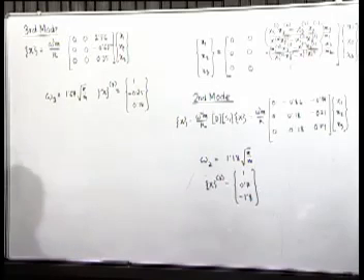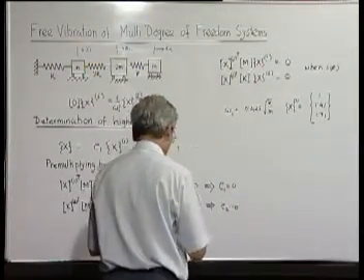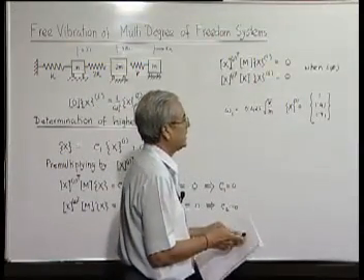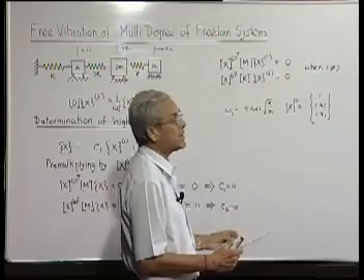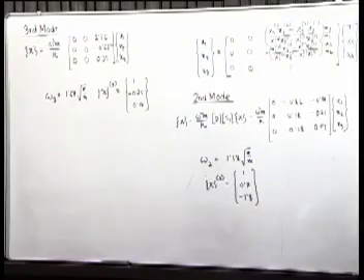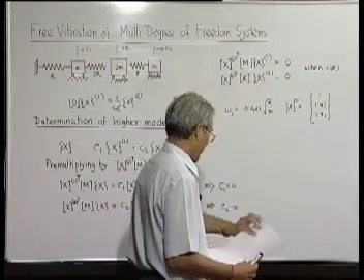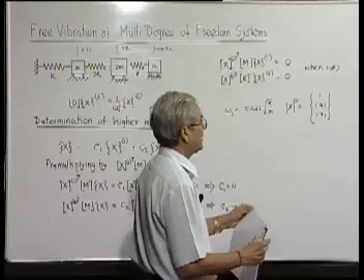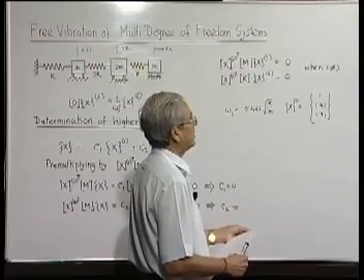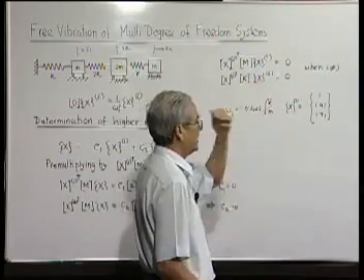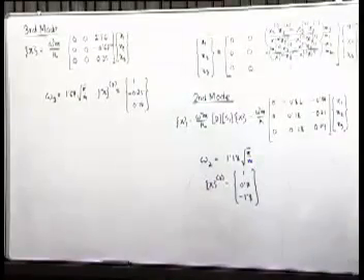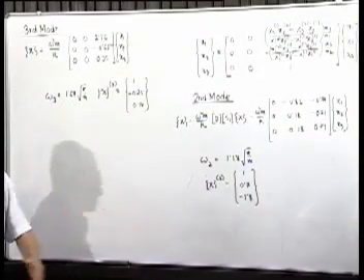So thus we get all the higher modes by using this sweeping matrix technique. If we solve a matrix equation directly, of course, then we get all the modes and all the frequencies simultaneously, but it is a very computer intensive process. Now you can see that even if it is simple, it takes some time.